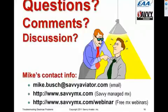All right. Gary has some fluctuations in voltage readouts. He's got a JPI analyzer and a Davtron clock. In flight, the readings never match. JPI is always lower, sometimes to the point of momentarily giving an alarm, 12.2 volts. The ammeter always shows charge, and the battery minder shows a full charge. Does he have a problem, or any ideas that might be causing this?